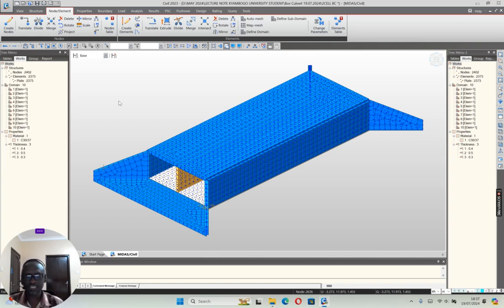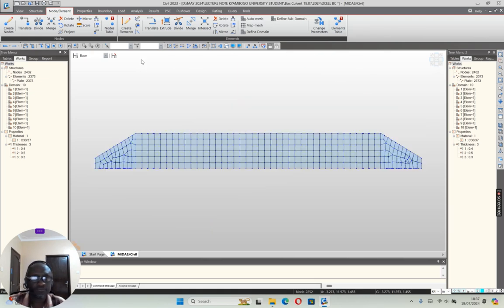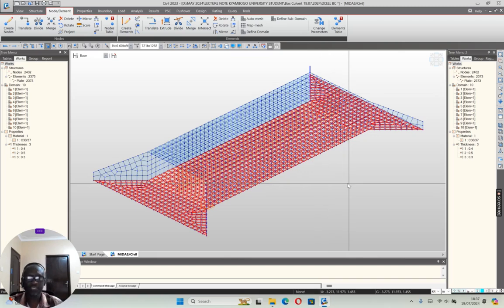So for boundary conditions, I think here there are 2 things. I'm going to use rigid. Rigid connection means all the foundation will be fixed, and then I do a rigid foundation where I fix only the base. If it is flexible or elastic, then I would do, because of soil structure interaction, you should be able to apply some spring on the sides of the wall and also the base. But for now, we shall do on the side of the wall. So I just make sure I apply. I do that, remove that, then I highlight, I activate the base.